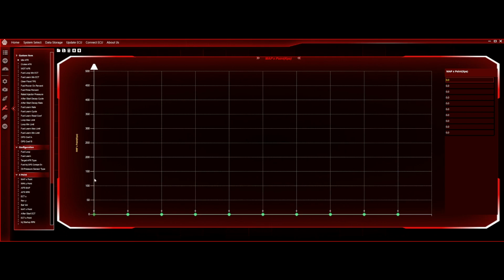Now I do 105 because your pressure can vary a little bit, and you don't want to go over the top and not have anything there, especially if you have a very high efficiency engine. You can actually get above 100 kPa for tuning purposes, for your VE tables and stuff. So I tune it up to 105. You'll see that on some other maps.